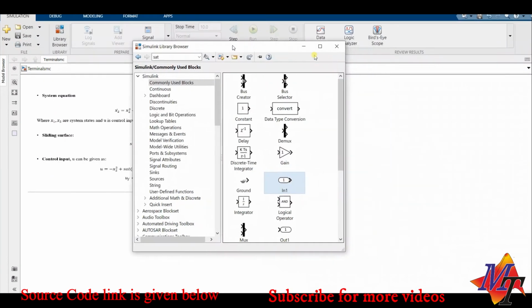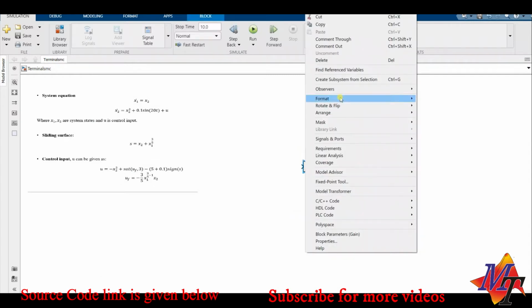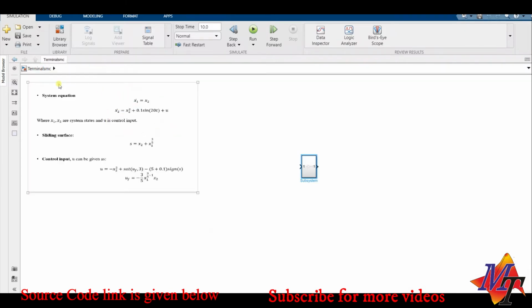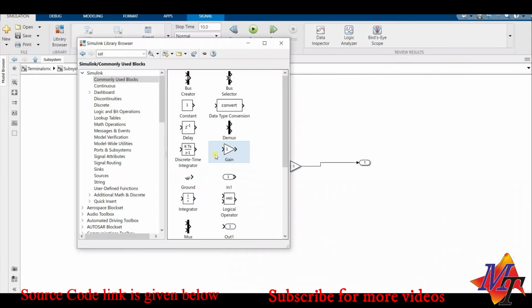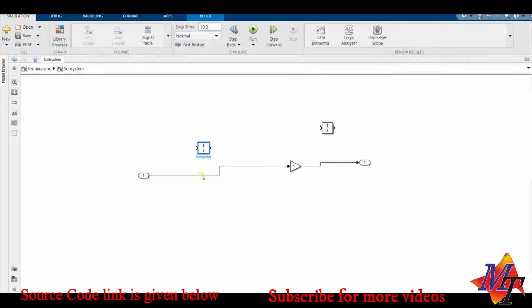In this section of the video, we will start modeling the system equations for the given sliding surface that is terminal in nature. Then we'll start developing the control input. First we'll make a subsystem for the plant. Okay, so we'll start modeling this, that is x1 dot is equal to x2 and x2 dot is equal to this. So for that, first we'll take two integrators. First we'll take integrator x1, then we'll take our integrator 2.